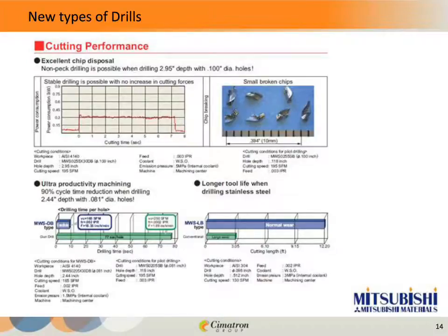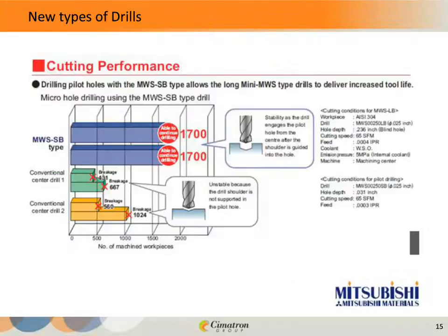Okay, next, a lot of these tools are going to require a pilot hole in order to keep the tool engaged. I mean, this was always true of gun drills, but even with the solid carbide tools, when you get a diameter to length ratio, again speaking in generalities, probably above 5 times the diameter, you're probably going to want to have a pilot hole in place to keep that drill on center and on size.